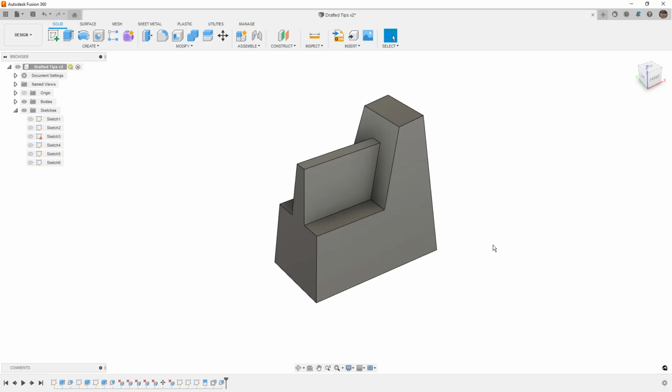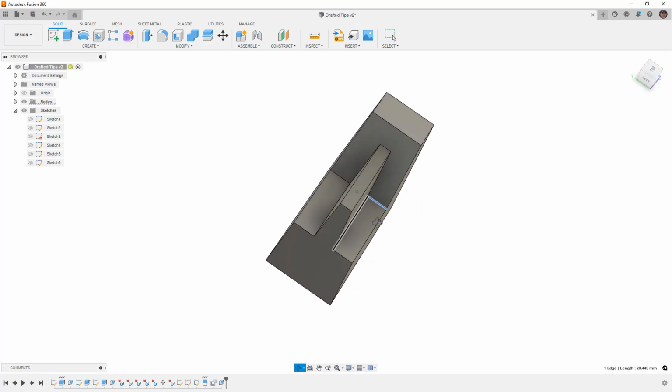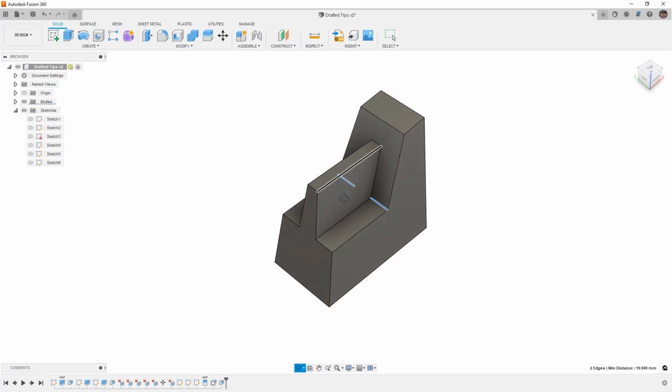So it's always a good idea to first give a shot to doing things like using delete to clean up those edges rather than going back and trying to fix those features, and by using things like split face to try to build out any additional ribs or features that will help match the existing taper or angle of faces. Now these examples here, these were all done using lines and straight faces, but they could have had angles, they could have been rounded, and it would have worked just the same.